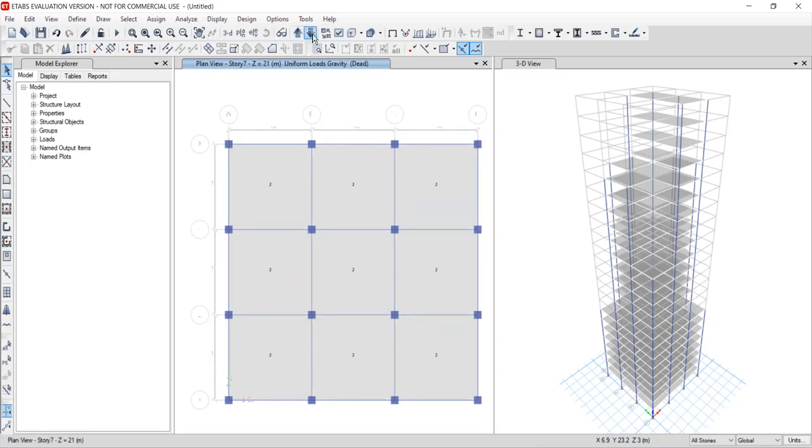Now we have to apply live loads at different sets of stories. So we will use the similar story option to assign the live load. Here we will go to similar story. Now select these cells. Now we see, cross check it, 72 cells, 9 cells in one, and they are 1 to 8 story, therefore 8 9s are 72, therefore 72 cells have been selected.